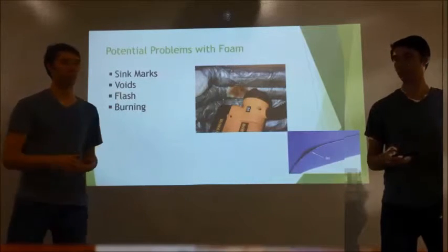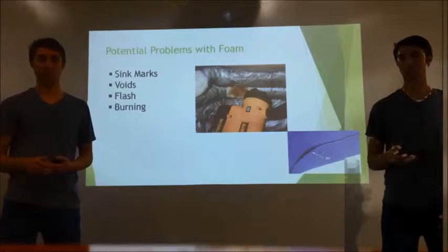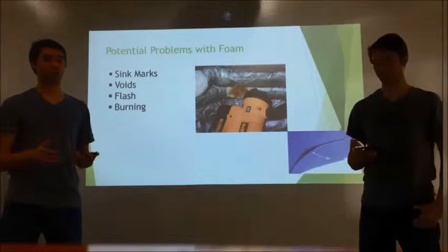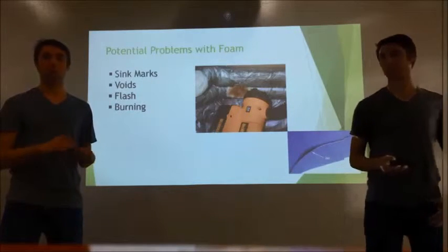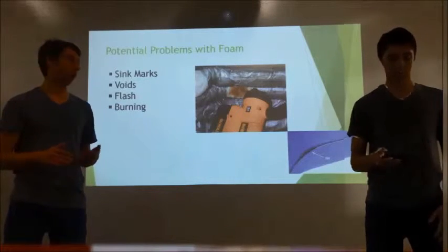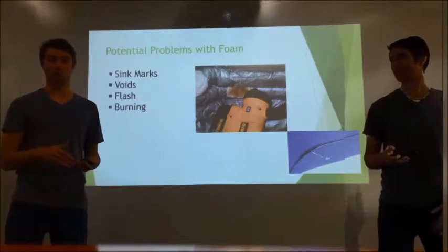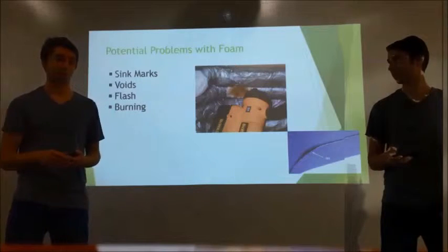I also have voids. Voids are similar to sink marks except they're more severe. Voids are large holes in the foam, which is no good when you want either a smooth surface or when you're trying to fit two things together. Also, it degrades the structural integrity of the material that you're trying to produce.